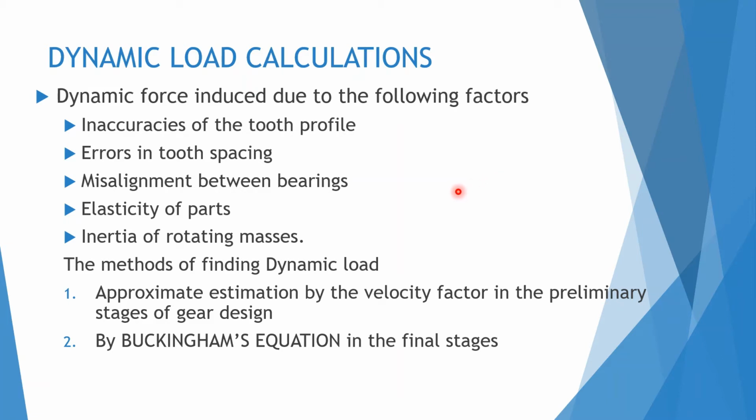Next one, dynamic load calculations. When a gear rotates at slower speeds, the tangential load Ft itself can be used for design, because there are no other factors to be considered. But when the gear drive starts rotating at a higher speed, it is necessary to calculate a dynamic load for the design, and the dynamic load is induced due to the following factors.